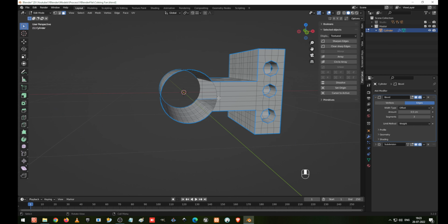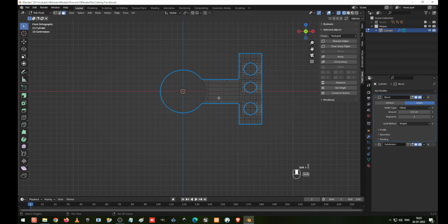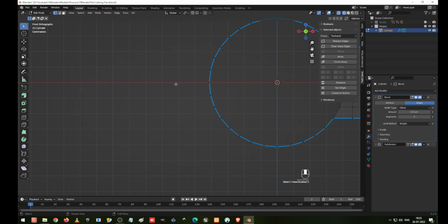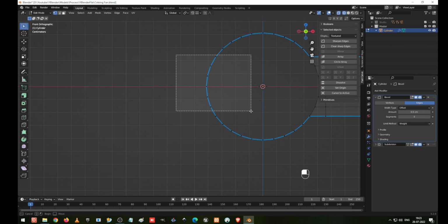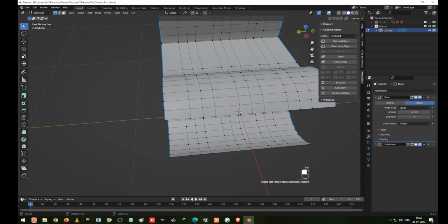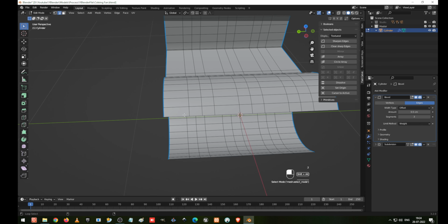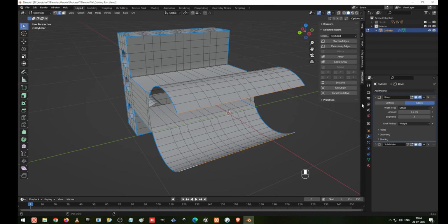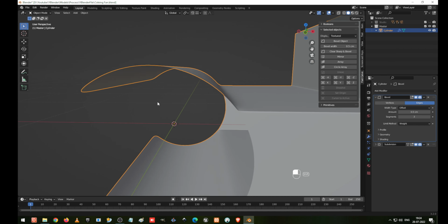Okay, now it has been deleted, and go to the side view and wireframe, and go to the vertices option. I'm going to select these vertices, three from here, three from here, middle one, and yeah, correct. Yes, X to delete the vertices and go to the wireframe. Go to the edge selection and select these edges and make sharp edges and go back, and it looks better.